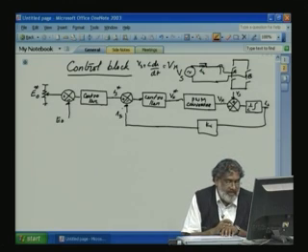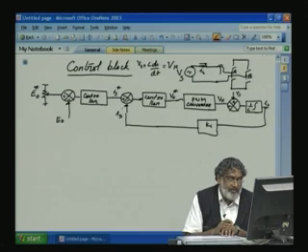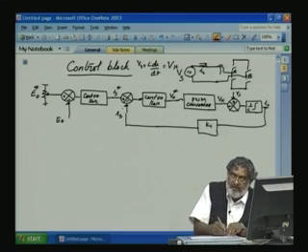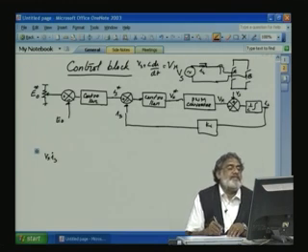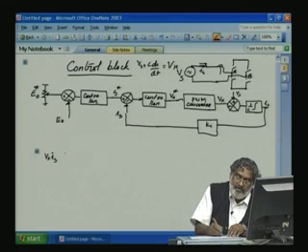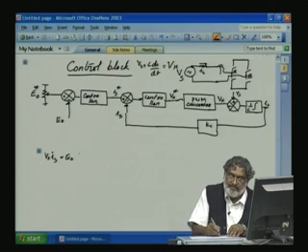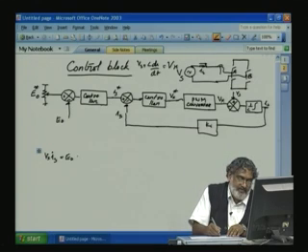How do you get the E0 value? How do you make the block diagram for E0? From the power balance, with unity power factor, Vs Is, the RMS values, is equal to E0 into I0.